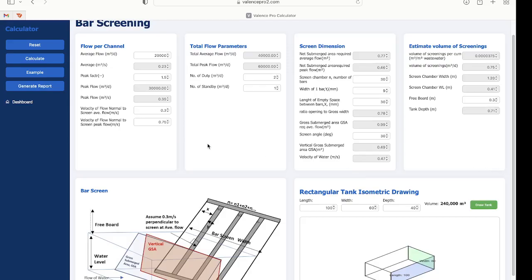So if you can refresh your trigonometry, a flow of water, although it has this direction, can also have a direction at an angle depending on what angle you have. So this velocity has different flow at different angles. We just want that at this vertical area here, the velocity of water is greater than 0.42 meters per second. So these are flow at an angle, so it's 0.3 and 0.75 meters per second.